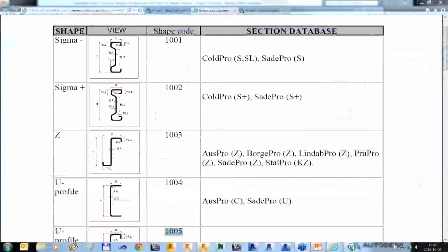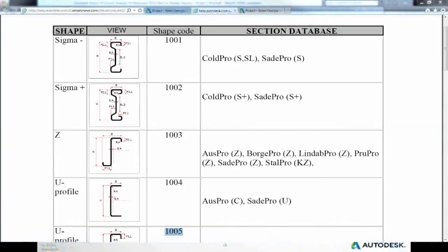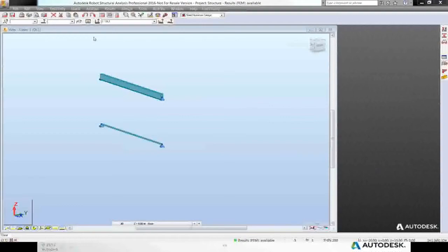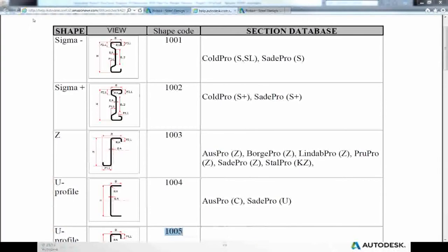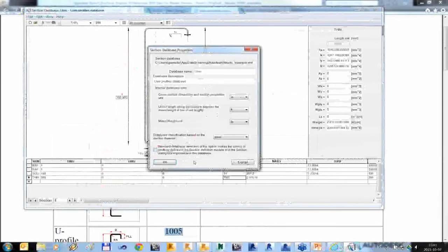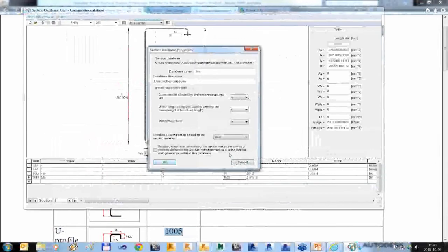So there was also a question whether it is possible to edit native or standard databases. The bottom line, it is not what we recommend. However, it is possible when you uncheck the standard database mark, which is available in the properties of the database. But personally, I'd rather suggest that you copy this database, give it a new name or a new description, and then edit. Just in case you make any mistake, you may return to the original file.